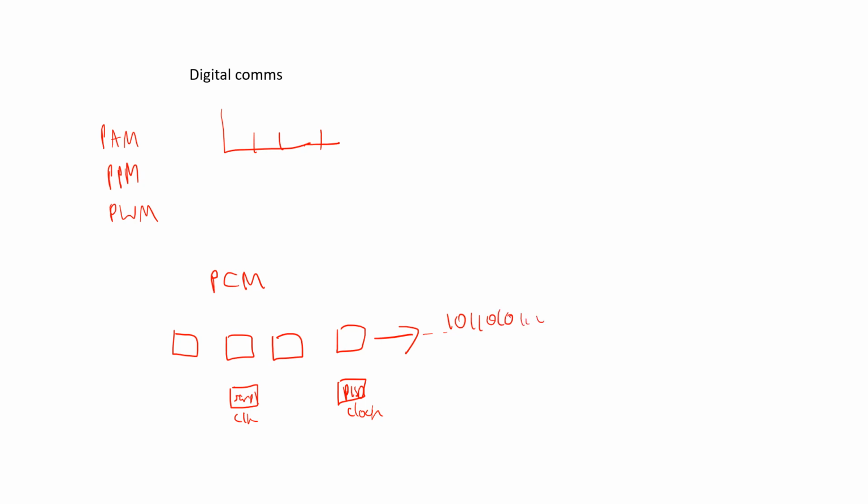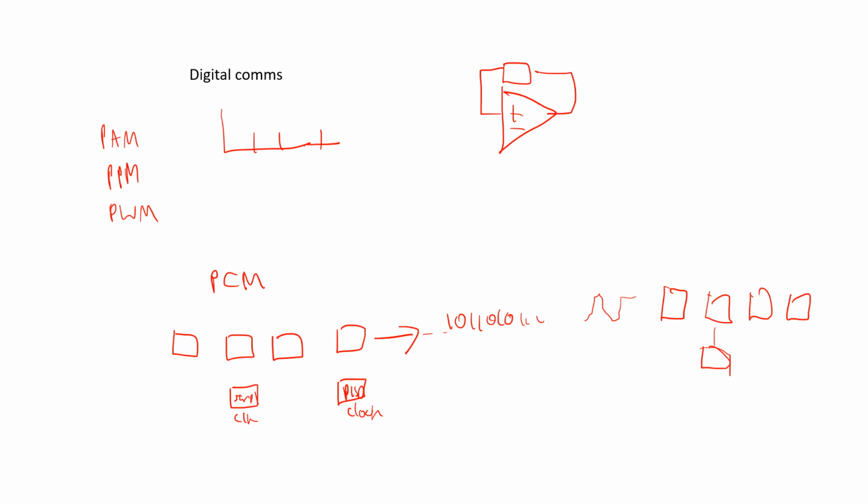Coming along. And then obviously to regenerate the signal at the other end, you might have noise and distortion. Do you remember that? To regenerate it, you can use your Schmitt trigger going on there. And then obviously it might look something like that. Look it up yourself. I'm not going to bother putting all those things in. With Schmitt triggers, you get asymmetric and symmetric. But remember the resistors, even though I told you the complete opposite for the last 2 years, you can put them the opposite way round. So you have positive feedback going there.